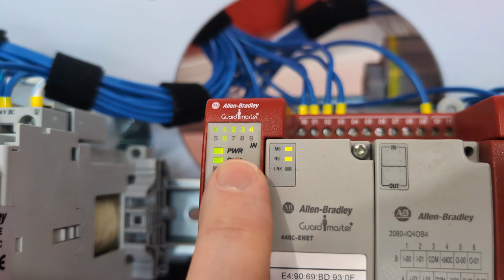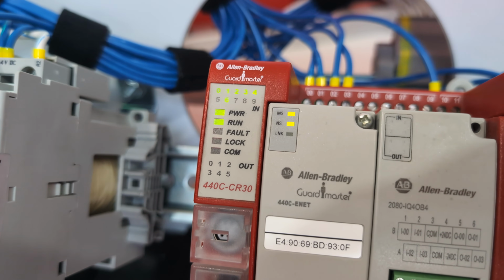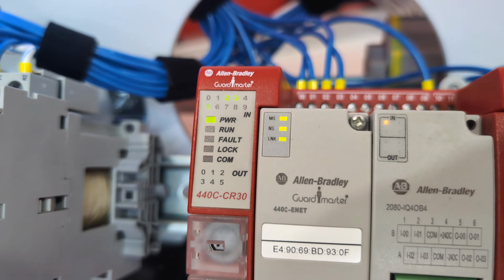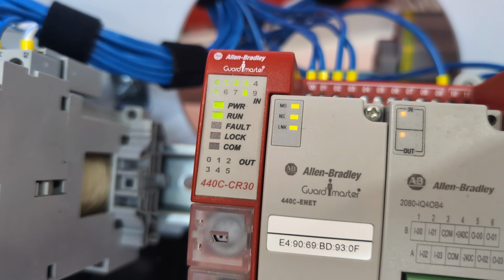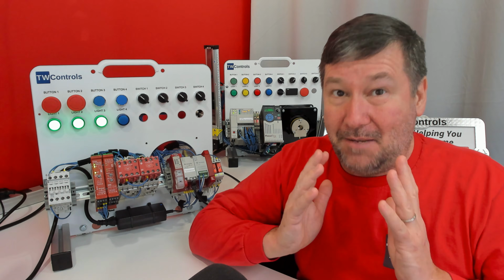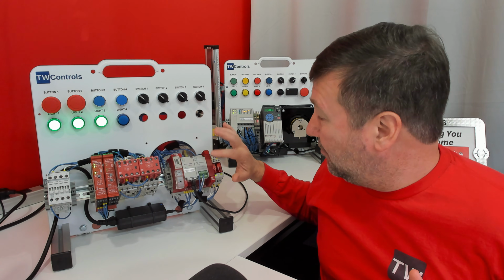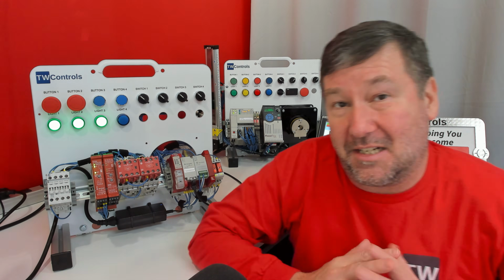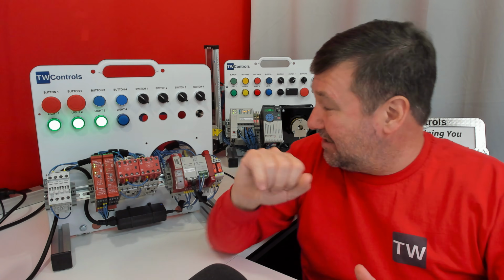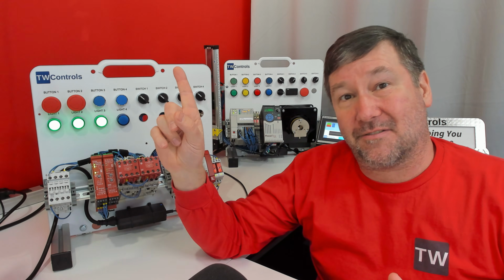So by having that, I can see right now that we're lit up through there, but if I press my first e-stop, that drops out 0 and 1. Also dropped out my safety output. Pull it back out, and we're good now, but it's waiting on a reset. So that can be a really fast way to glance over and figure out what's going on without even having to connect with Connected Components Workbench. So set up those LEDs, and also we can actually set this up in the I/O configuration of Studio 5000. And I've created this playlist right here that includes that video.